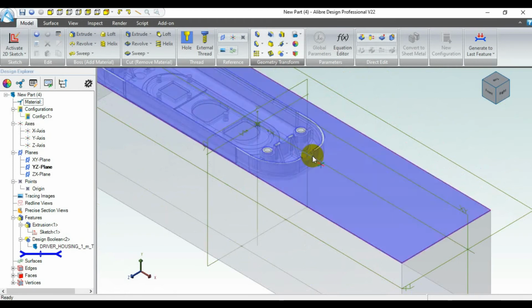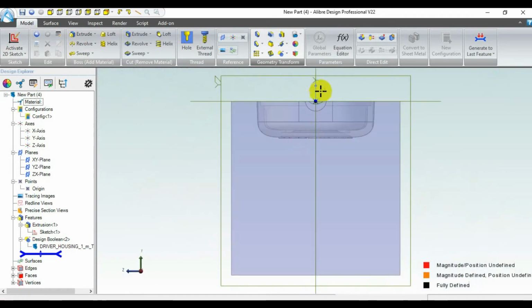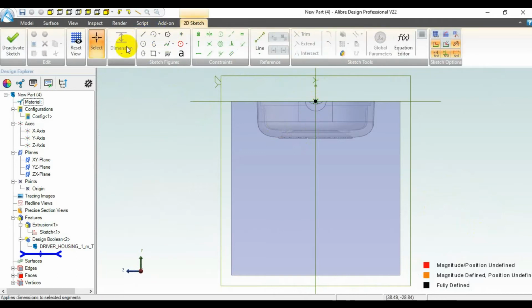We'll just use that cutout for purposes of making it work anyway. So we'll just go into sketch. We'll select this end face here, and you can see our part there. We're going to make a circle around our origin point there, and we're going to make this circle 6 mm in diameter.